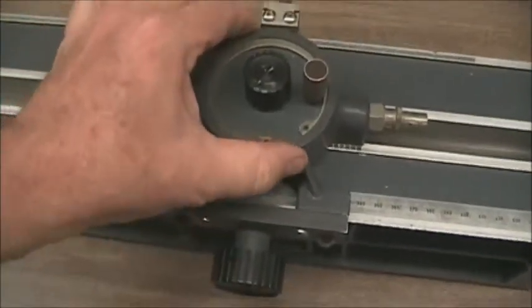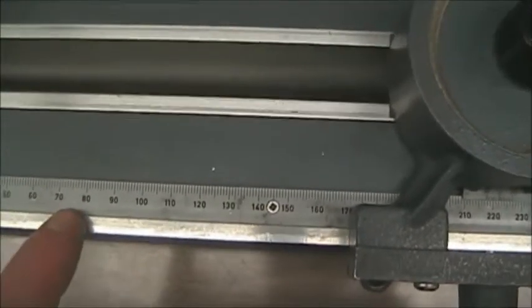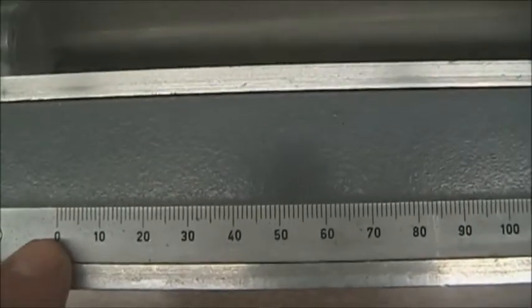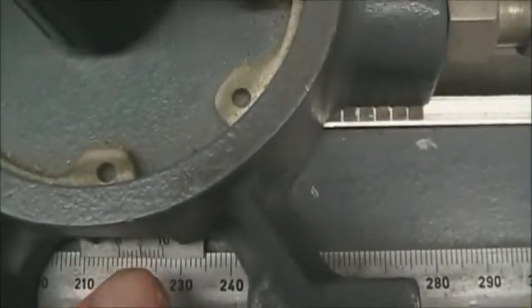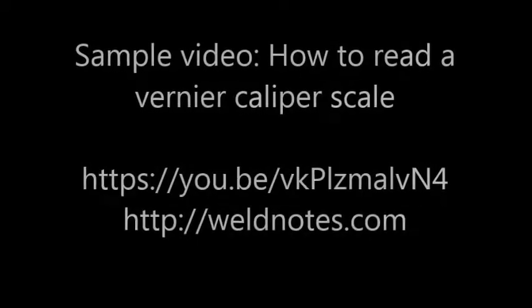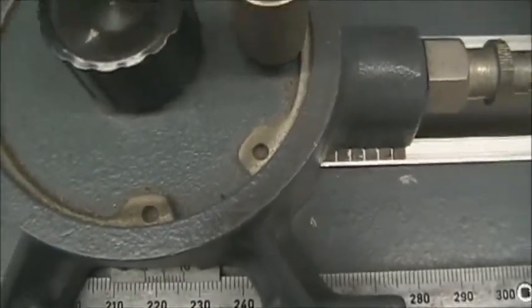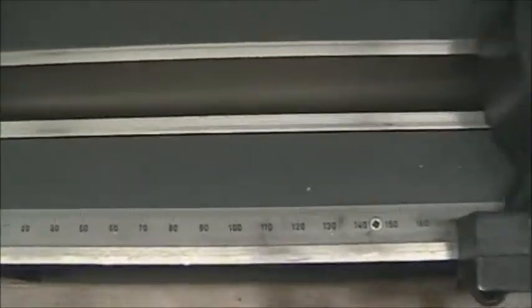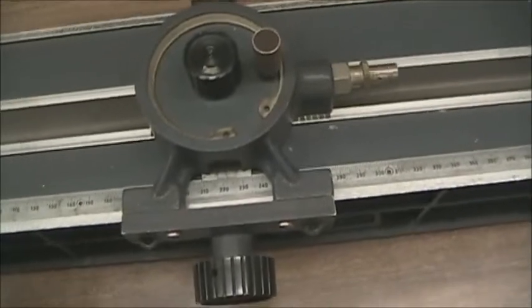And then we just move this along, and then we can measure, and we have a metric scale here. Each 10 is 10 millimeters, so each mark is a millimeter, and then we have a vernier scale, which, if you don't know how to read a vernier scale, gives you one more digit of accuracy there. So this unit is basically accurate to 0.1 millimeters. Very fine resolution. This unit could be used up to over 4 gigahertz.